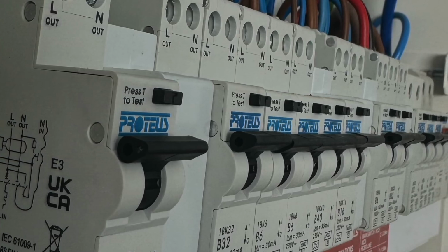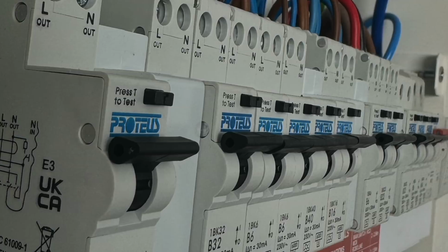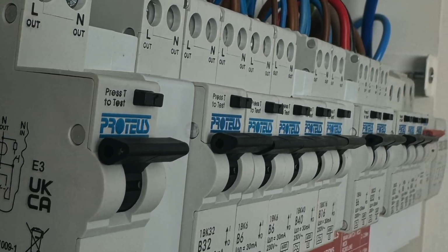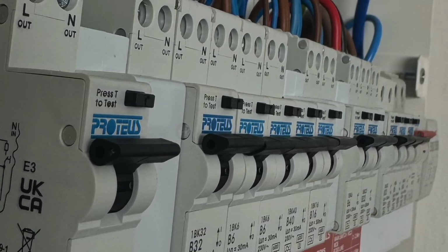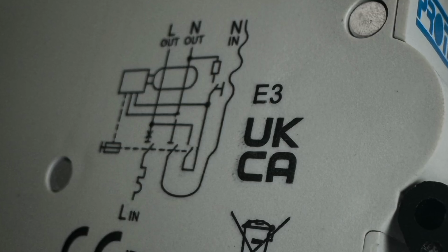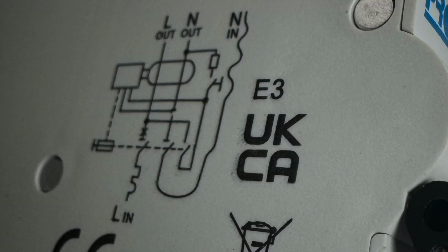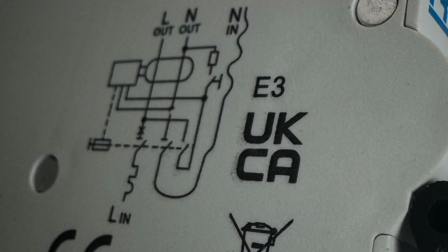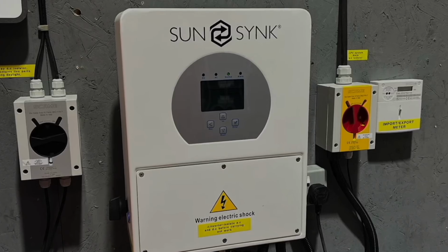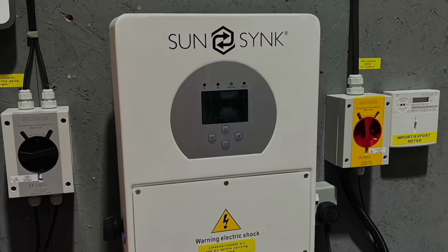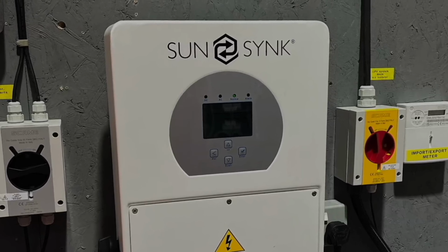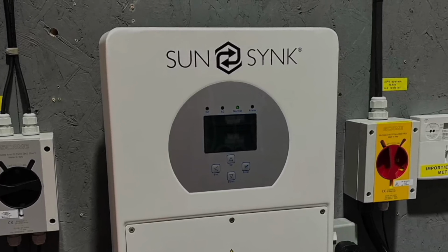Bidirectional RCBOs and MCBs are available from manufacturers, and as well as being double poled to switch all live conductors, they will operate if current is flowing away from the inverter towards the supply. But if you're unsure about any of the protective devices that you are fitting, then it's advised to contact the manufacturer. Many inverter manufacturers also fit residual monitoring devices in their units, which give that additional protection. The Sunsynk inverter we are using has a residual current monitoring unit, and I asked Sunsynk about the residual current monitoring devices in their inverters.